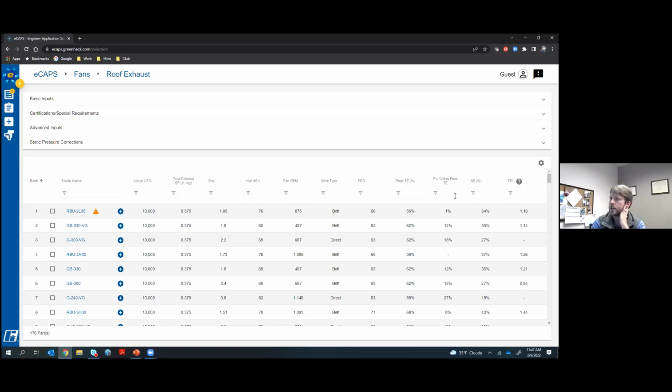Okay, great. Fan energy index gives us an unbiased comparison of fan choices. Does this mean that the higher the FEI, the more expensive the fan is? In other words, does the fan cost automatically track fan FEI? The overall answer is no. If I am comparing, say I'm in a warehouse where it really doesn't matter what kind of fan I need, I just need a fan that's efficient and a fan that has the performance, FEI would be a great way to look at, say, an axial versus a rooftop exhaust. And you're probably going to hit two different price points.